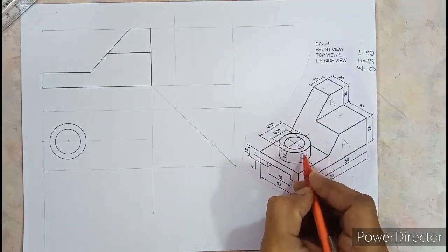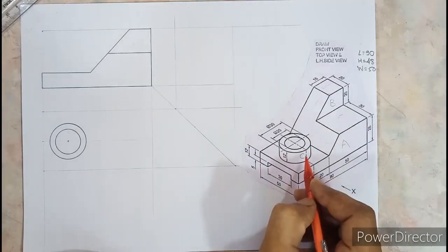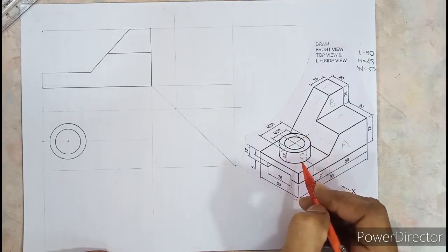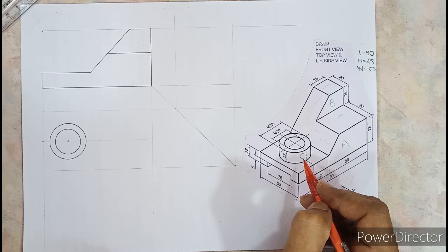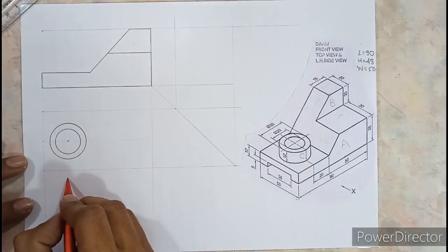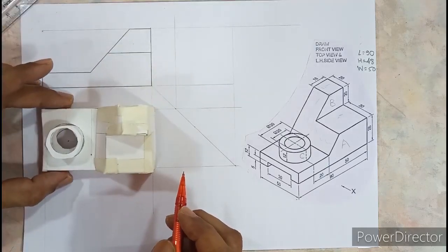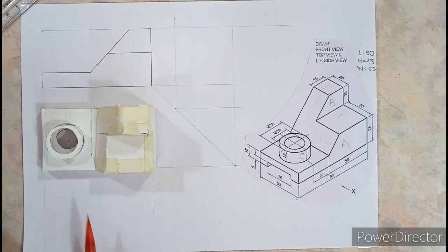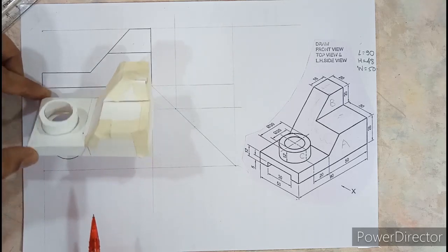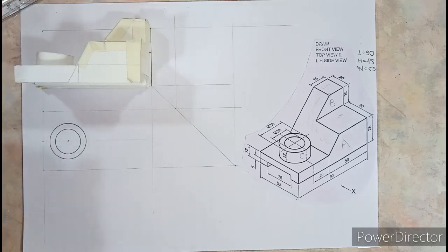Let us now focus on surface C. If you look at surface C, it will be seen as a rectangle. For that, try to visualize this diagram. You are the observer. Now see, this is the top view, right? And the observer is looking from this side. So when you look from this side, or if you turn the object, that is what you get in the front. So in the front view, that is how the object will be seen.